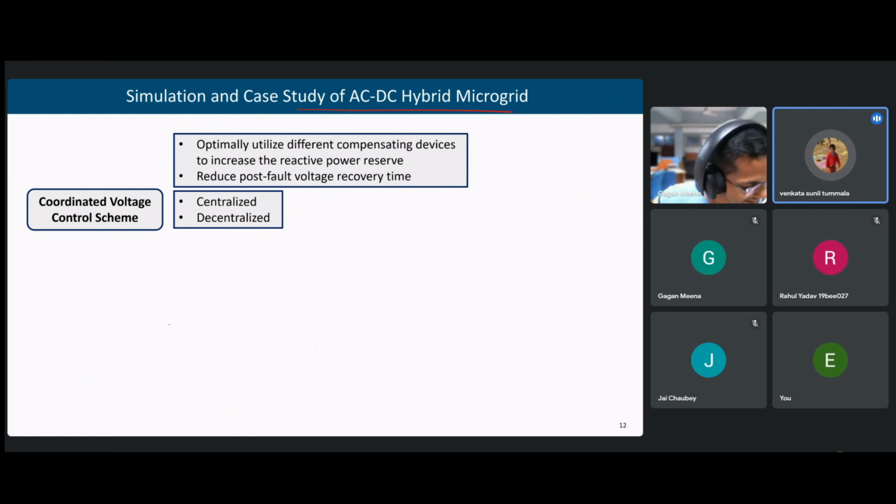But there is no other solution at 6.6 kV and 11 kV, so we will have to go for passive filters. We are not using voltage regulators in the distribution system. If we use that, that is one of the solutions. In India, we are not using that. They work on line drop compensation. Sometimes we are running our motors idly to compensate this.